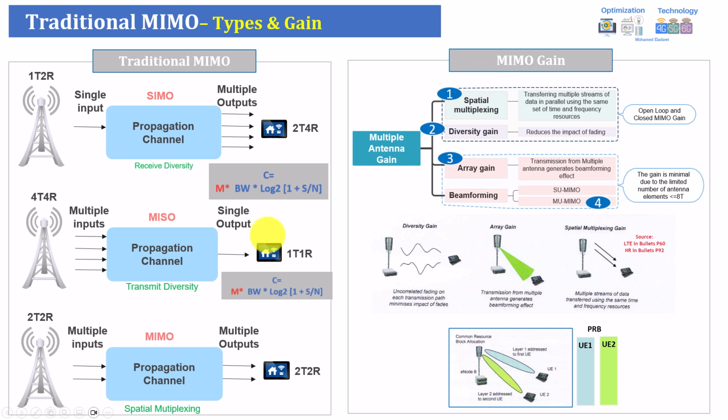So, in general, to improve the throughput or the capacity, you need to increase the bandwidth or improve the signal to noise ratio. And actually, diversity here is trying to improve the quality by adding additional antennas, either in the receiver or in the transmitter. Also, this M can be used during multiple stream transmission, so you can, for example, multiply this by 2. In the beginning, the formula was without M. But when you introduce MIMO, MIMO plays a factor in improving even the SNR, doubling the capacity, doubling the throughput whenever you have spatial multiplexing.